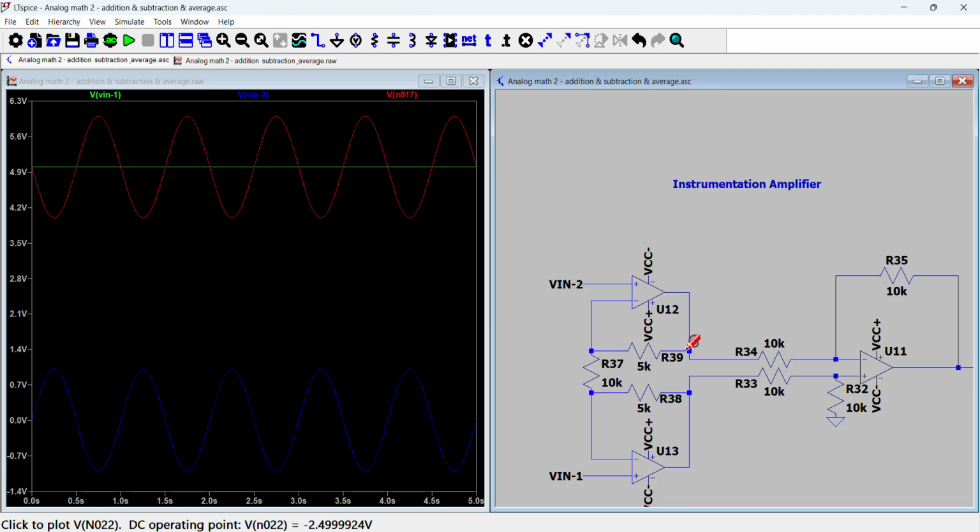And yeah, so I just went through the derivation with you, but obviously I don't have the ability to show the mathematics on paper. But you can follow my derivation and come to this conclusion that this circuit not only has infinite input impedance now, it also has a gain of 1 plus 2 times 5 divided by 10, which in this case is 1 plus 2 times a half, which is 2.